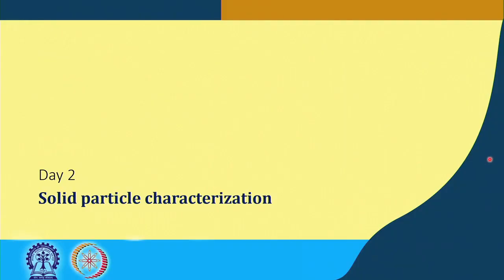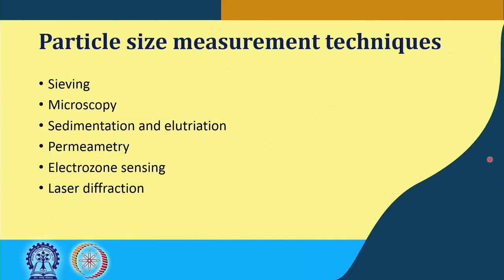Today we will go through the solid particle characterization that we started on day 1. At the end of day 1, I mentioned that particle size measurement techniques will be covered in this class. Those I mentioned the names as well are the sieving, microscopy, sedimentation and elutriation, permeametry, electrozone sensing and laser diffraction.